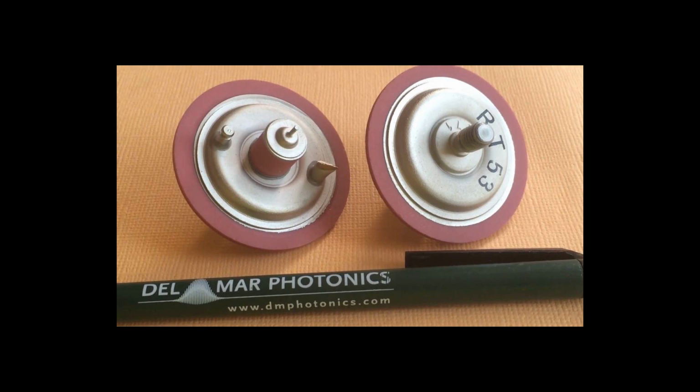However, due to energy losses caused by late-time ablation and rapid conductive heat transfer from the propellant to the rest of the spacecraft, propulsive efficiency, kinetic energy of exhaust over total energy used, is very low compared to other forms of electric propulsion, at around just 10%.